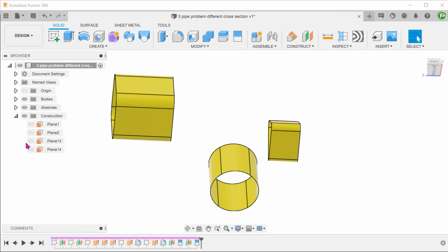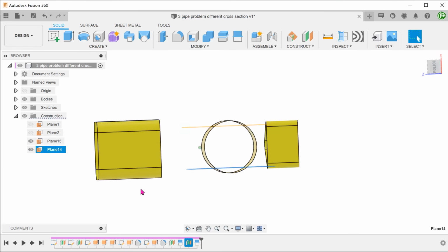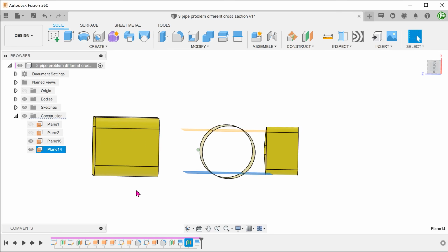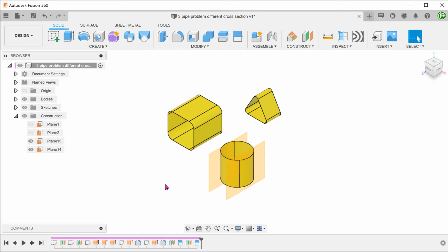For the cylinder, I have created the split lines in the same way as in the previous video. I have also made this file available for downloading in the description. Just roll the timeline back to just before the first loft to follow along. Let's create the bridging surfaces.